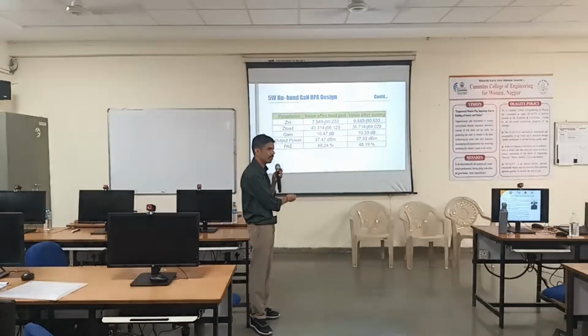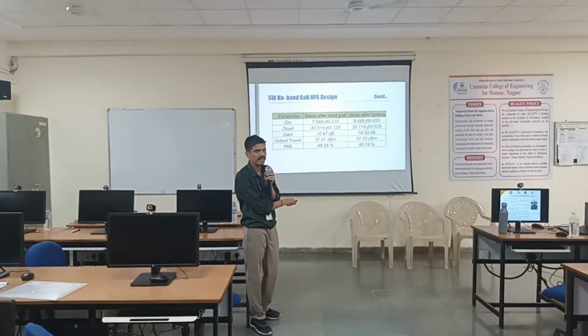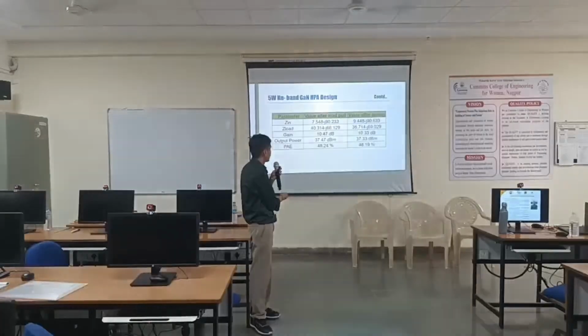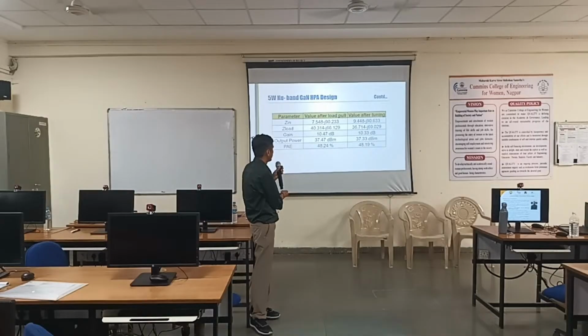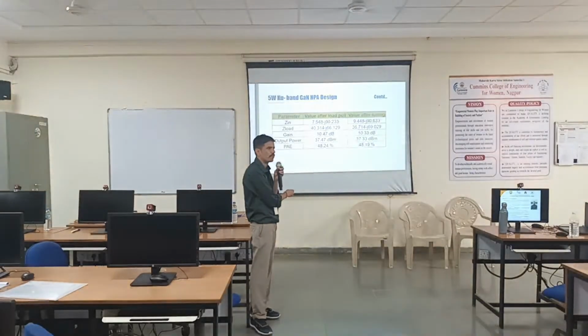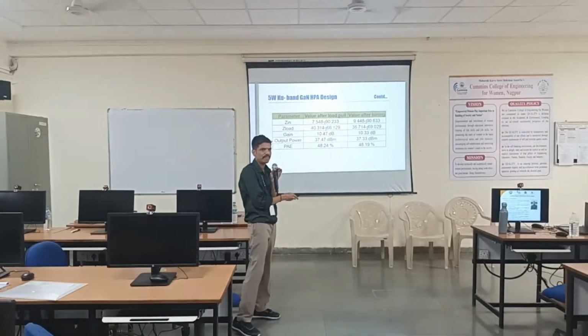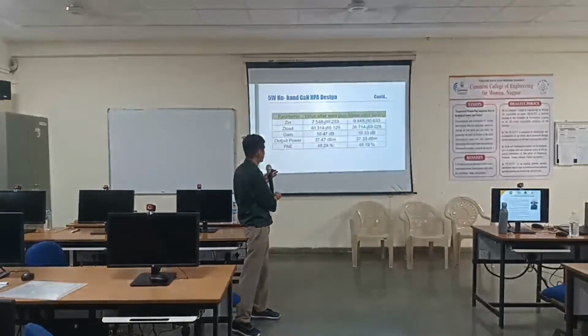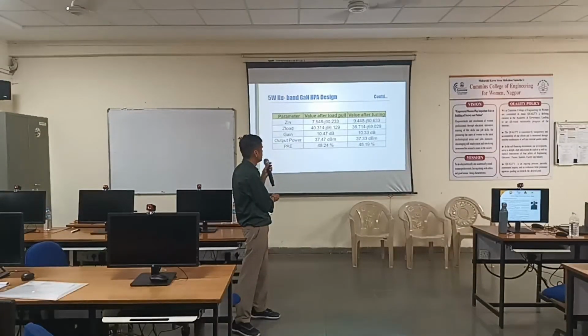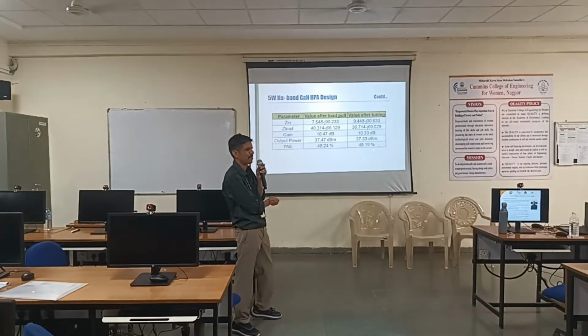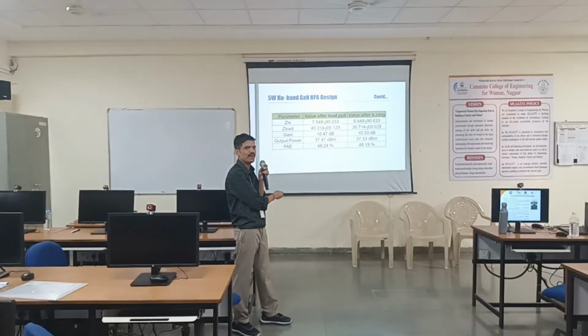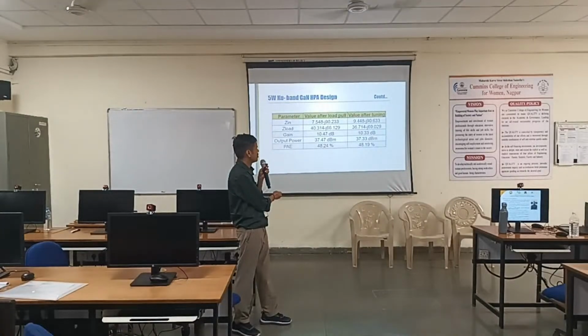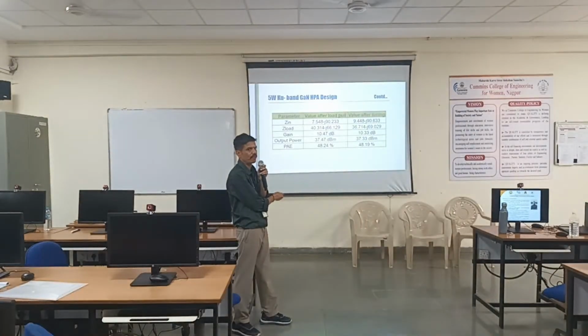Then I did some further tuning. There is a specific reason. I have tuned them because I know if this number has jumped from 7.5 to 10, 12, that is okay for me. But at the cost of what? You cannot simply change these numbers and optimize. At the cost of gain. I am losing just 0.1 dB of gain. I am losing just 0.1 dBm of output power, and in efficiency there is no compromise. So I can go ahead with these numbers also, so that this job can become a little simpler for me.